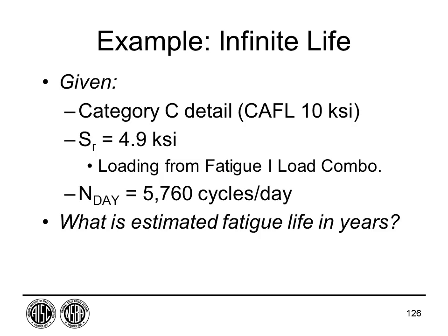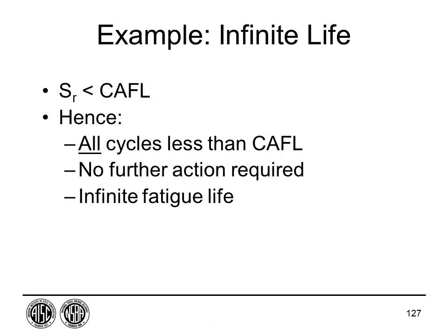For infinite life, these are even easier. Same category C detail, rather, different detail with a stress range of 4.9 ksi. This is from my Fatigue I, so this is my infinite life check. I have a lot of trucks per day. What's the fatigue life? Well, I realized that my stress range is less than the fatigue limit.